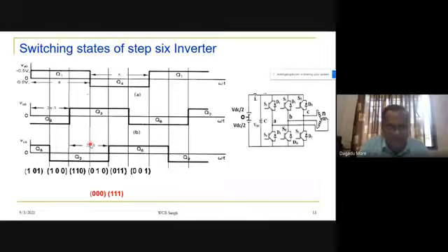In PWM inverter or space vector PWM, these null states are present. So the output of sinusoidal PWM and space vector PWM is definitely less than the 6-step inverter or 180 degrees mode of conduction. So is it clear? Today we discussed the concept of the voltage space vector and how to obtain it. Any questions?